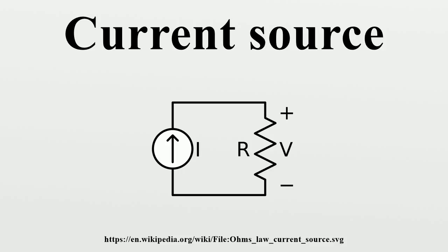Current-regulating tubes. Nitrogen-filled glass tubes with 2 electrodes and a calibrated Becquerel amount of 226Ra offer a constant number of charge carriers per second for conduction, which determines the maximum current the tube can pass over a voltage range from 25 to 500 V.